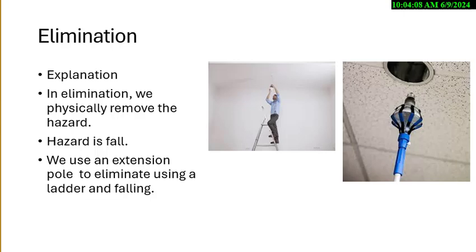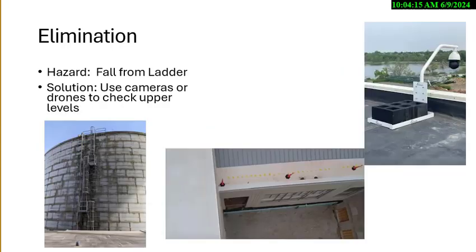You'll get examples asking which of these five methods is being used, and you'll have to be able to catch that. Here we're going to go up on top of the tank. We have a ladder that's provided with cages. Cages are not fall protection by OSHA; they're just something that came up in the 50s. OSHA wants positive fall protection. Offset the platform every 30 feet. If you're climbing a fixed ladder at 24 feet, they require something protecting the worker, usually a ladder safety device. But if we need to inspect it,